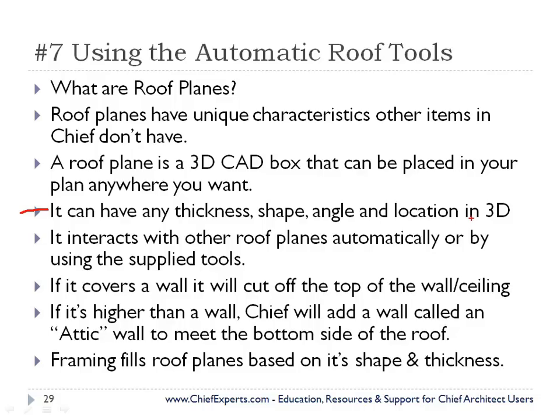Doesn't matter if it's over a wall. You don't have to have anything in your plan, and you could add roofs. It doesn't matter. Roofs are their own thing. Roofs interact with other roof planes automatically or by using the supplied tools. If a roof covers a wall, it will cut the top of the wall off, unless, of course, you've stretched that wall up, and then it won't get cut off anymore.